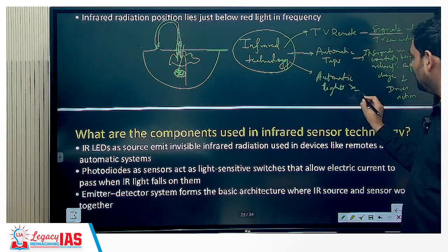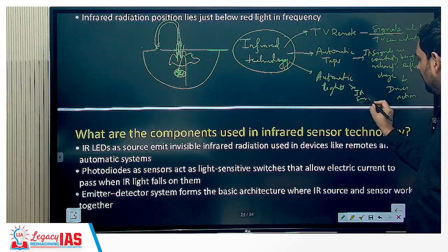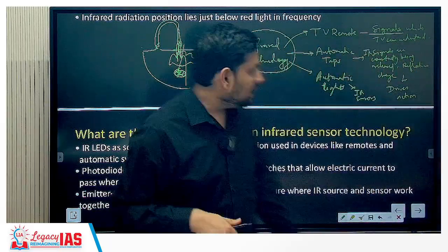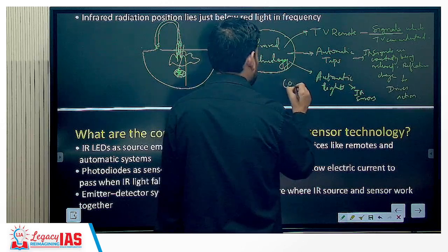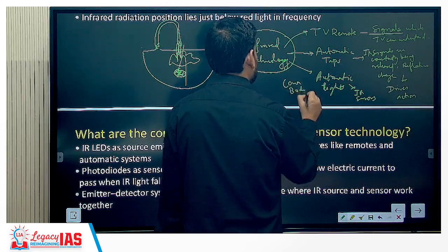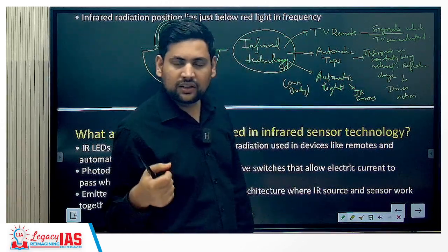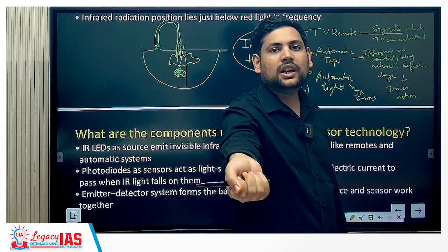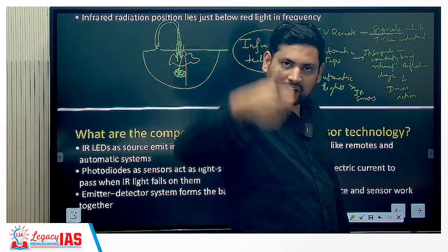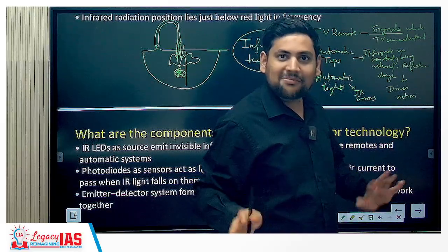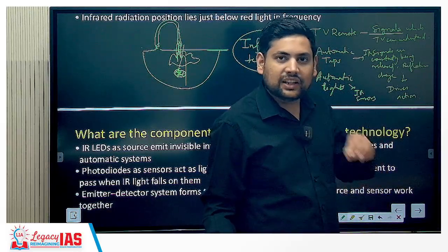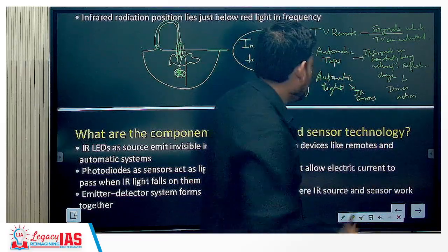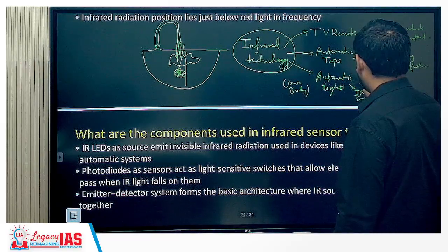So what they have is sensors, infrared sensors. Now these are passive in nature. That means infrared will be released by our body. We are emitting infrared radiation. So if I move inside a room, I will release that infrared radiation. Now the detector can detect that infrared radiation towards it has increased. That means a human may have entered, and it will turn the light on.